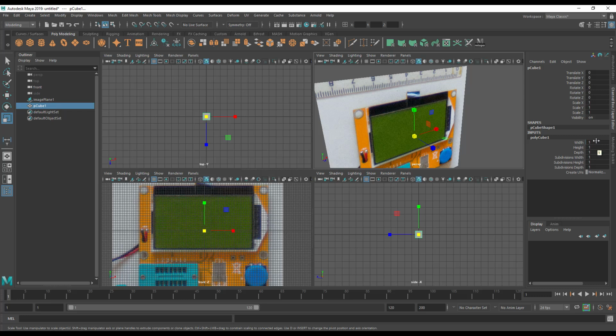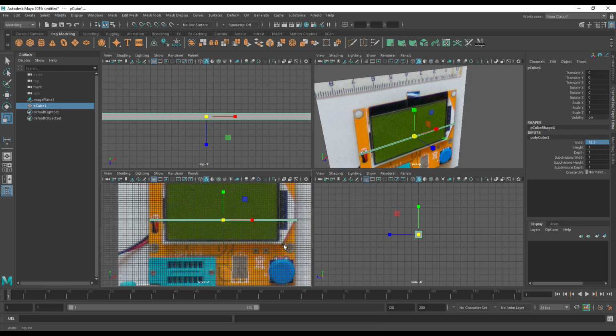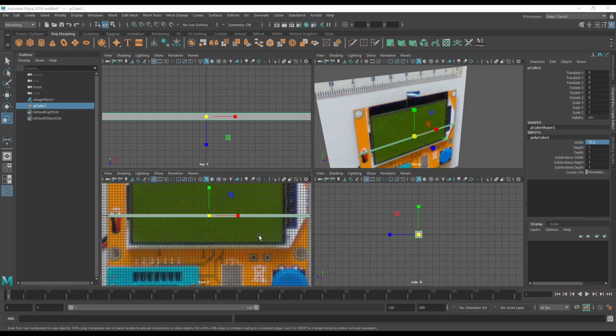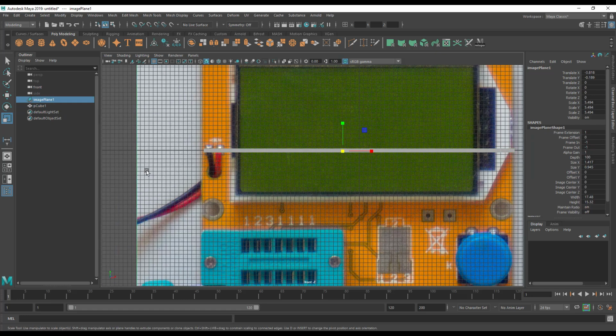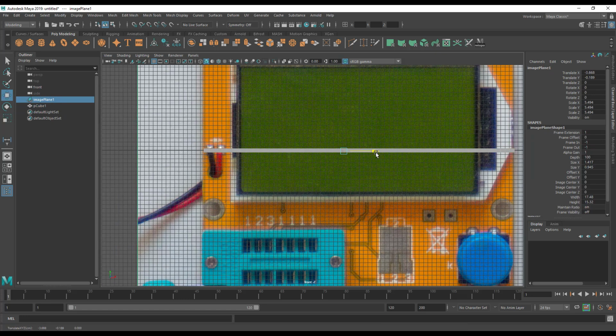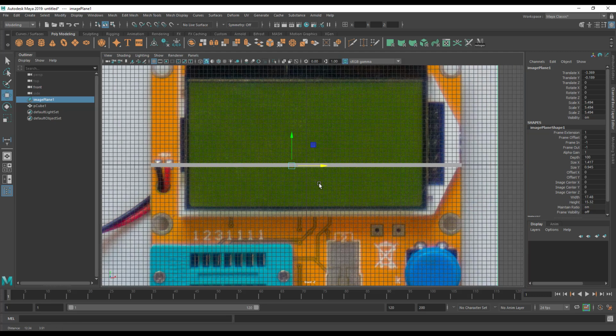Now this is going to be in millimeters for us. If you're using feet and inches, you might have more of a hard time with it. I would generally recommend for something like this that's going to go to a 3D printer that you use millimeters. But you know, your mileage may vary, it's not a requisite. So width for us is 72.5, we know this from our measurements, and look at that. So we almost precisely managed to match the reference here. I would say something went wonky with one of my measurements, so I'm actually going to move this a little here, and there we go.